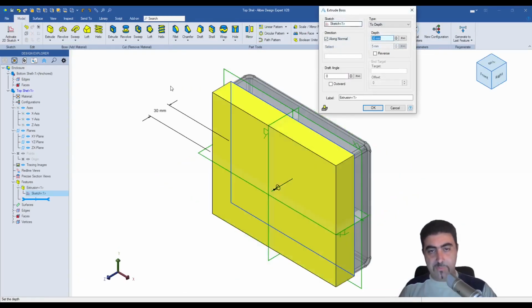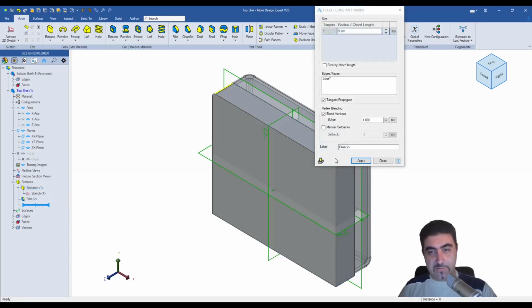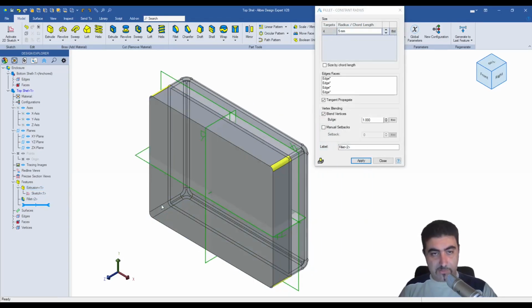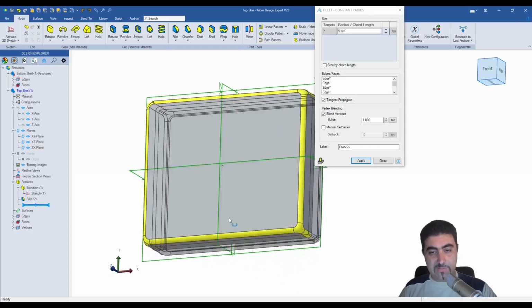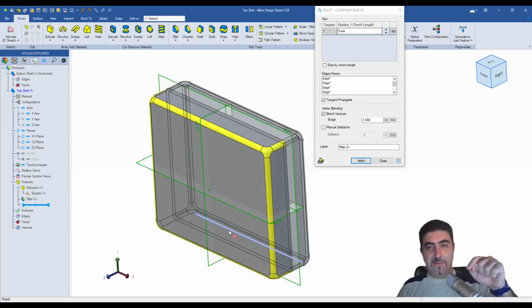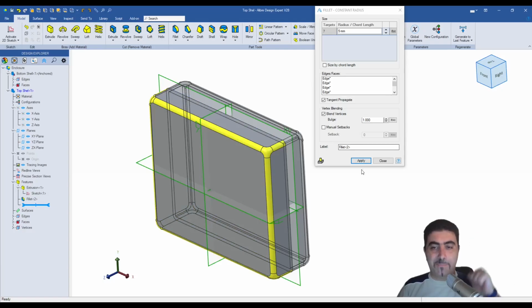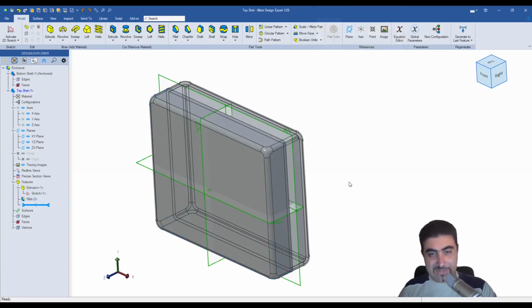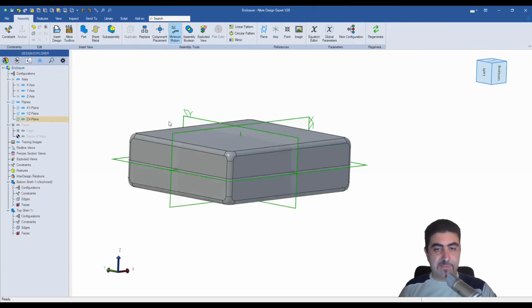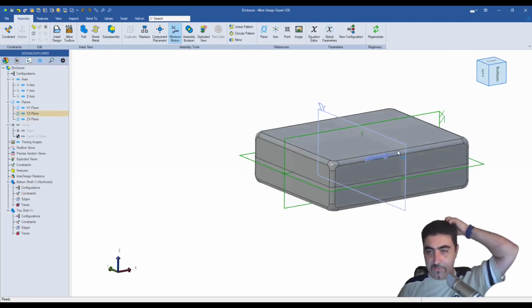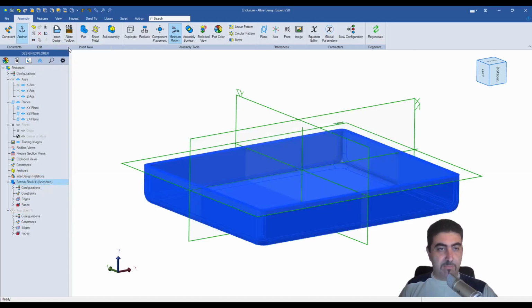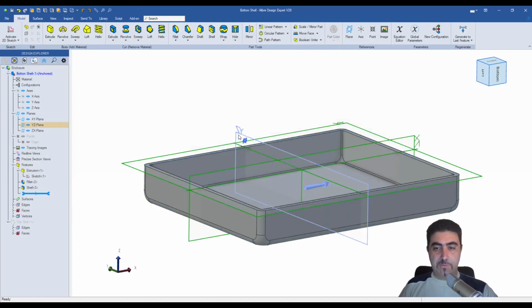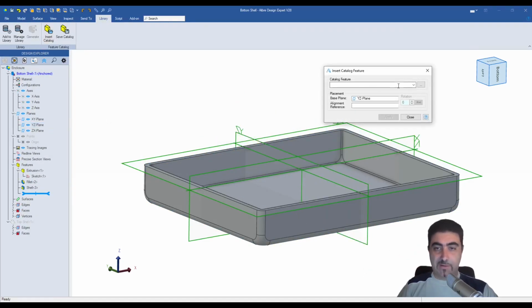So, and we'll extrude that for another 30, and we'll fillet it around. Now, here's one top tip. Because I am using these fillets, because I'm doing top-down design basically, Alibre remembers the fillet settings from the previous part. Okay, that made my life slightly easier. I'll edit my assembly again, and I have my 2 pieces of the assembly. So now I'll hide my top shell. I'll edit the bottom one, and I want to insert my catalog feature here, right?